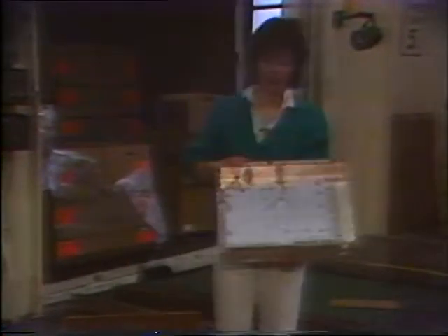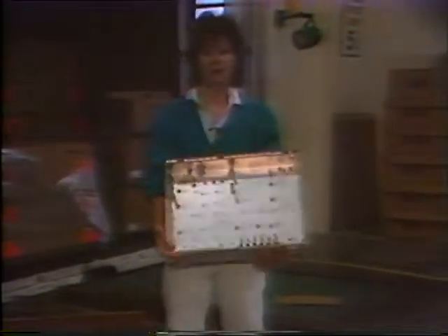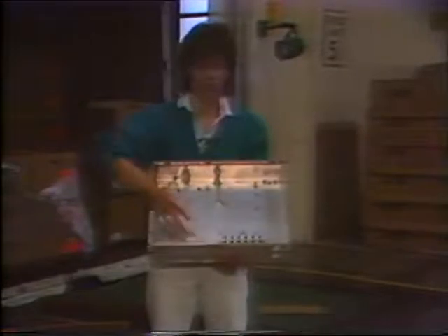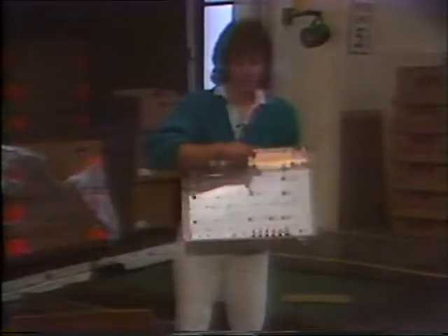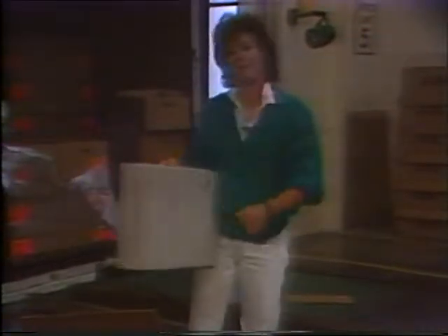What we have here is a Mac 2 bottom. And what you see here is a piece of sheet metal and a piece of plastic. The packaging starts with the sheet metal supplier, and the sheet metal supplier stamps out this piece of sheet metal here. They will put this sheet metal in this box with partitions. You'll see that 4 tops are in this box. The sheet metal supplier puts 4 of the sheet metal parts in the box and ships it to our plastic supplier, who molds this injection molded plastic. They heat stake the sheet metal into the plastic, do prep work such as add printing, logo, and put it back in the same box with the same partitions and ship it to Apple.